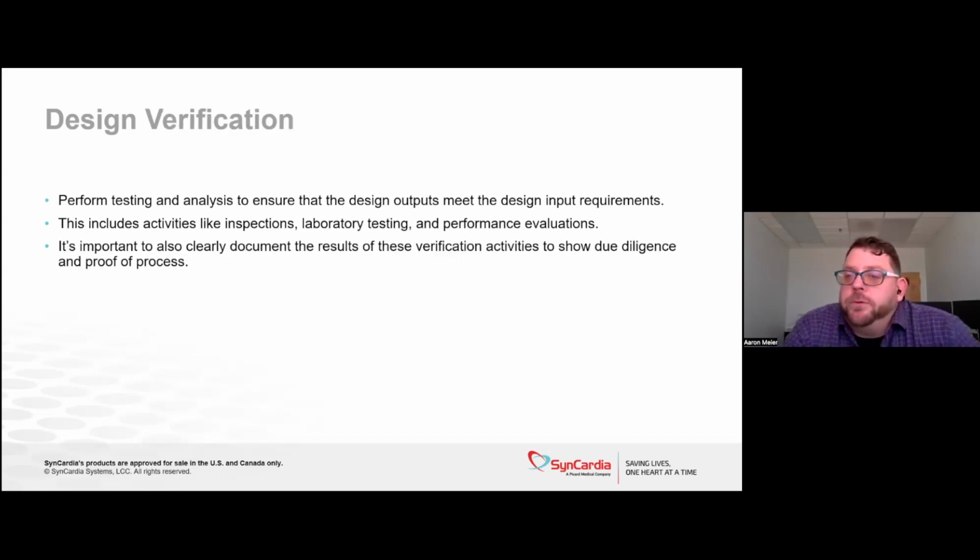So once you've gone through the design input and output process and you think you have your design, now it's time to demonstrate that you actually built the thing you tried to design. That's where you get to design verification. Do your design outputs match your design inputs every time? So that means if I design a driver that it needs to sustain 120 beats per minute, the battery has to last 6 hours and it has to be in an environment where it can be up to 100 degrees Fahrenheit, 40, 45 degrees Celsius.